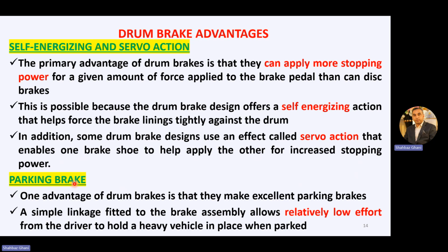Now, in the case of parking brakes, one advantage of drum brakes is that they make excellent parking brakes. A simple linkage fitted to the handbrake assembly allows relatively low effort from the driver to hold a heavy vehicle in place when parked. So drum brakes are usually used for parking brakes in old vehicles. Now, due to advancement in technology, we have the electronic parking brake system, and we will study this later on.